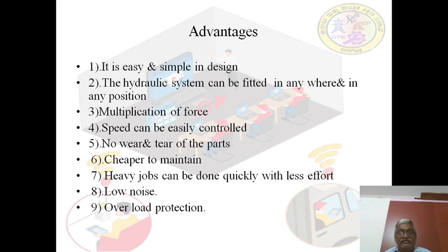Again, it is easy to provide overload protection. Suppose any member of the hydraulic system is overloaded, then there are pressure relief valves. They relieve the excess pressure, and then the excess oil is returned to the oil tank. Thereby it provides overload protection.